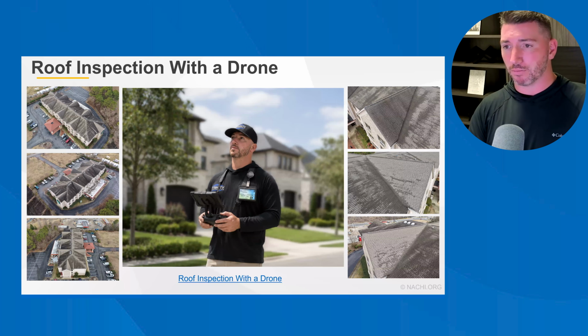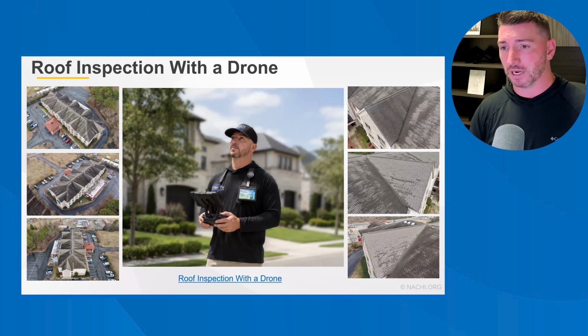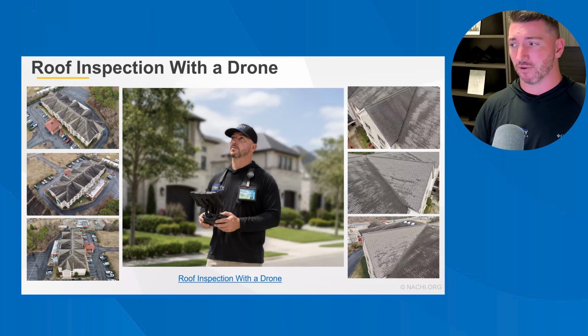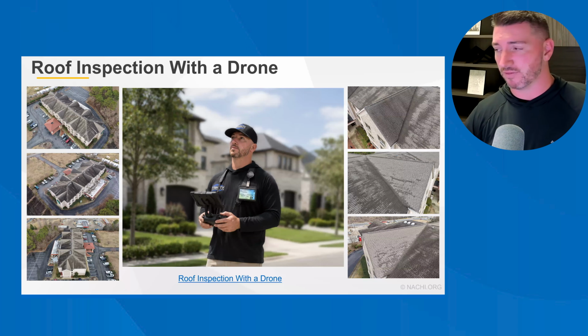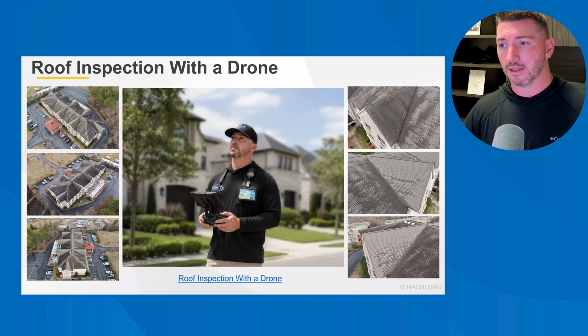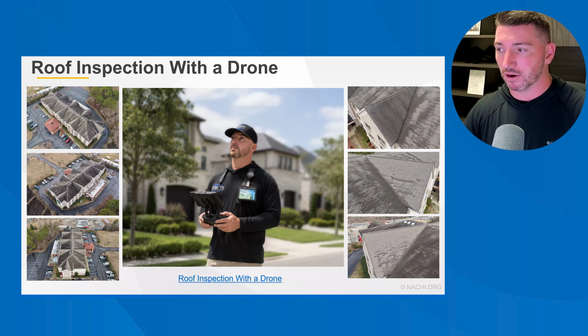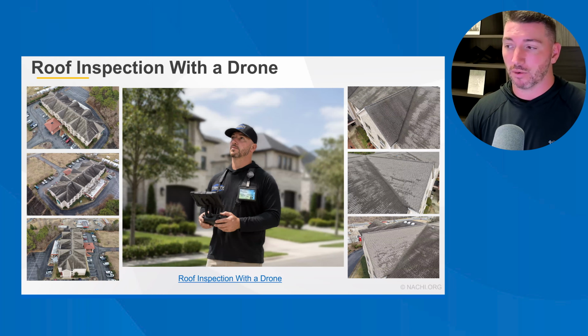Get your Part 107 drone license if you're going to be doing it to make money. If you're doing a home inspection and you're flying a drone, you need to have your Part 107 certification through the FAA. It's a great tool to use for very large roofs or very steep roofs. But if you don't understand some of the principles that we already talked about today, then you're not going to know what to look for with the drone, and you're going to be accountable for the information that you include in the report. So you're going to include some really fancy pictures, and if you can't speak to what they're of, and if somebody else spots a defect that you didn't spot with that fancy camera, then you're going to wind up in a bad spot.